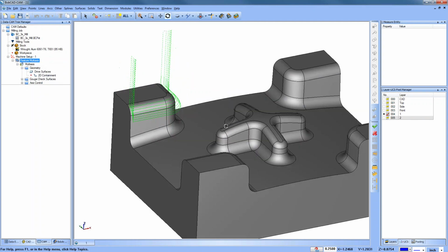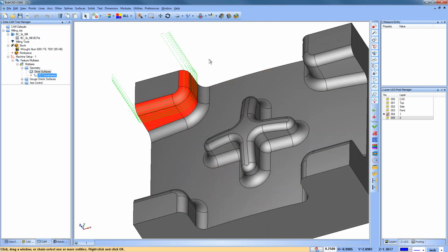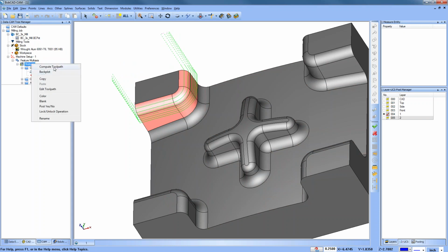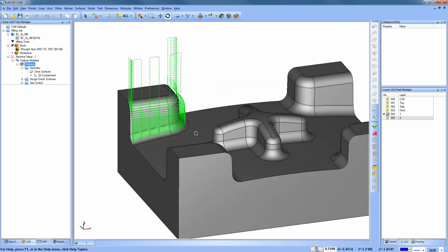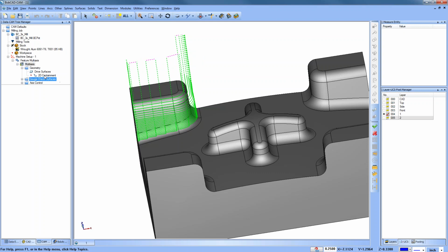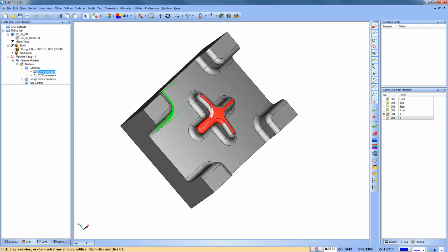Okay, so here you can see this is a Z-level style routine. I can add some additional surfaces. If I want the tool to go further on down the line, I can add more surfaces, and you can see it generates more toolpath. Now, let me remove these surfaces and grab a different group. Maybe I'll grab this section here.